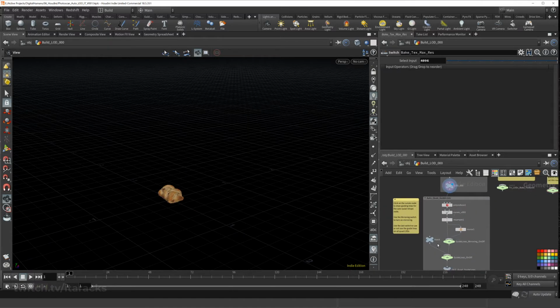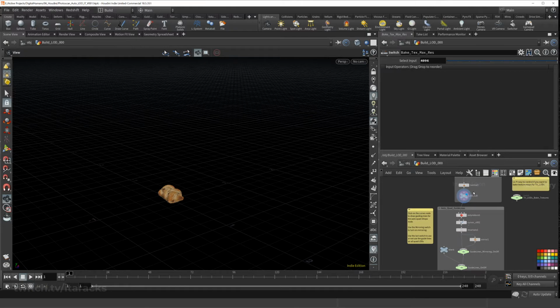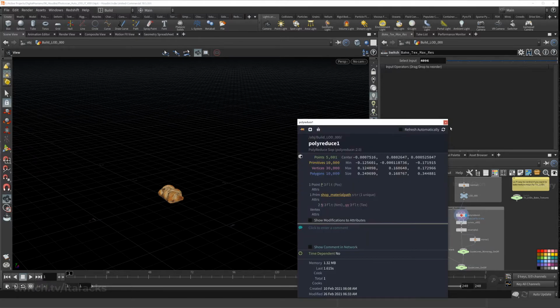After that is an optional kind of adjustments that you can add or ways that you can help the quad meshing. The quad mesher node that Labs comes with allows for guide splines, and in this case what will happen is you will take the mesh, and because sometimes the mesh will be from a photo scan and have upwards of 3 million or so, even higher polygons, it is almost impossible to paint or draw any lines on that in the viewport. So this just takes it into a poly reduction and reduces it quite a bit. So now we're just left with 10,000 polygons.